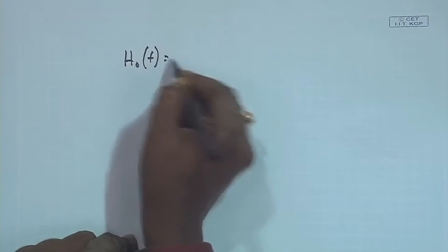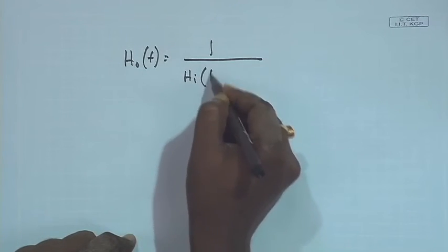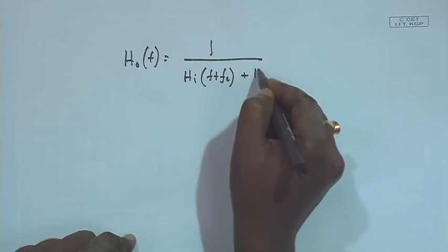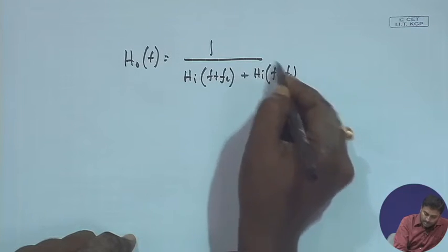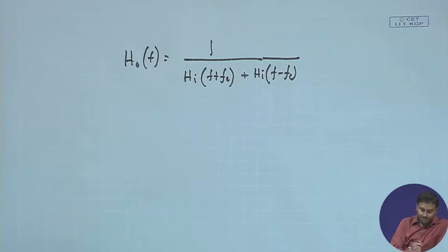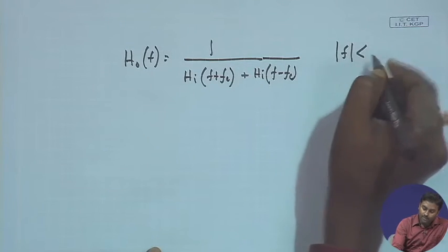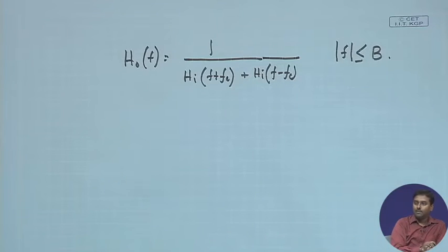Okay. Alright, so in the case of VSB-SC, we have already seen the input-output filtering characteristics and their relationship. So let us just assume one particular filter. We have already seen this relationship, H_OF is 1 by H_IF(f+fc) plus H_IF(f-fc), right. This is something we have seen, okay.